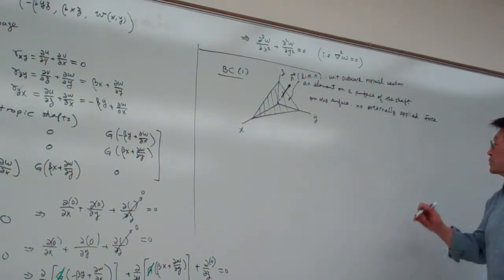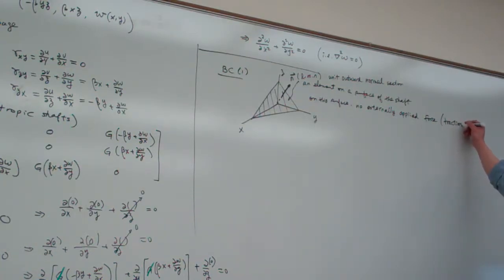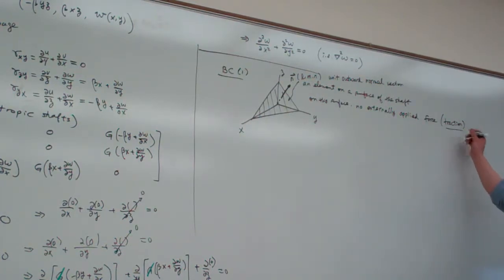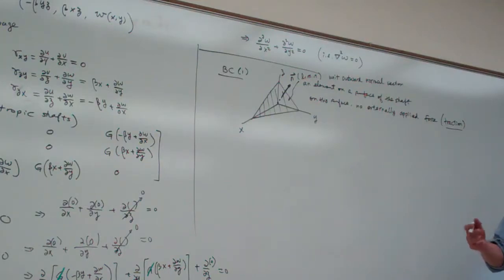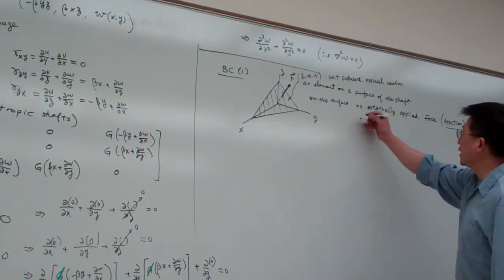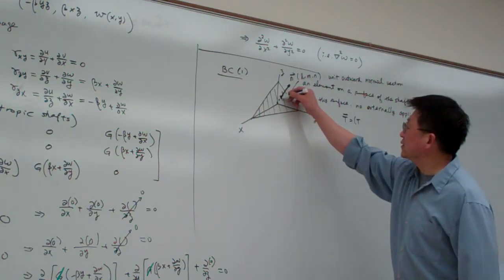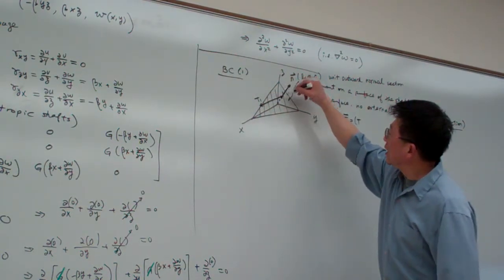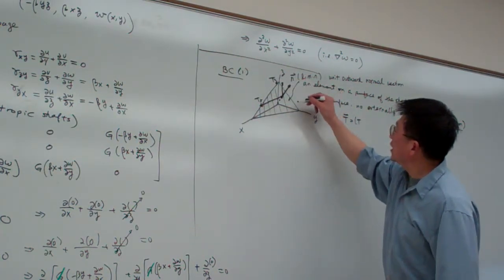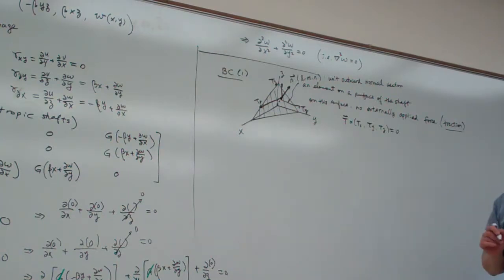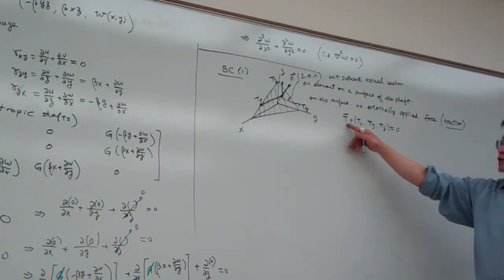And usually people use the name traction to indicate the force applied to the unit area. So basically people using this word are indicating the force per unit area, which has a similar concept to pressure or line load. Here we have no tractions. On this surface the traction, for example Tx, Ty and Tz, equal to 0. So no externally applied traction. We simply use notation T as a traction.